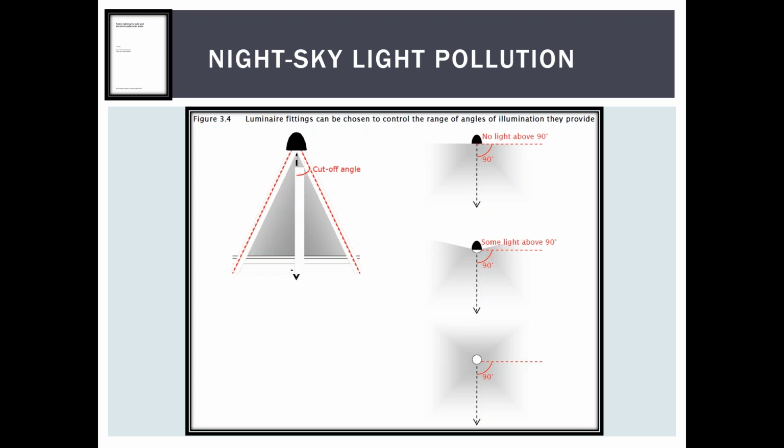As an aside, the 90-degree cutoff, which many agencies have gone to, has in some cases resulted in spotlighting and provides less light uniformity and consistency on the road, and may require, as a result, more frequent light pole spacing or light sources.